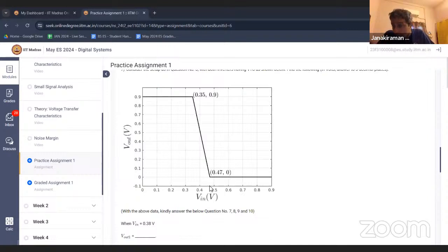That is the beauty. That's what I'm trying to tell you. That is the beauty of this CMOS inverter or TTL inverter. It is so resilient to noise. Even if the first inverter sees some noise, it gets nullified by the second inverter, and the voltage gets restored back to logic levels correctly.